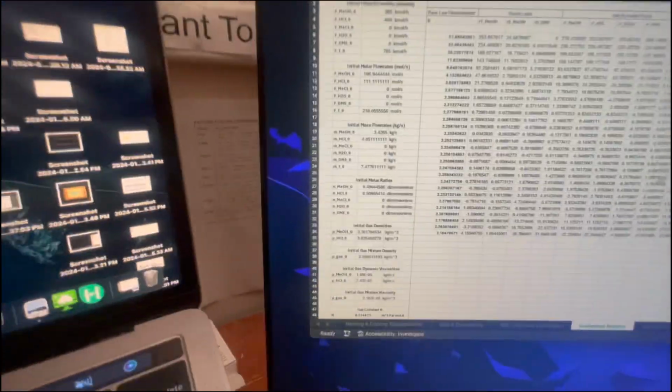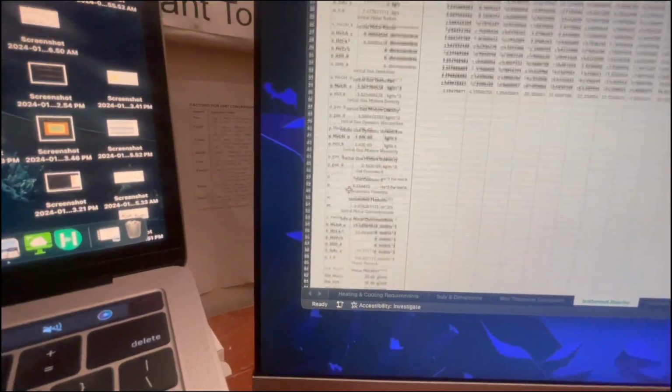The only thing is the reaction rates are pretty high, because those rates are found using a micro reactor. A micro reactor being very small, it doesn't take long for the gas to disperse and react. So the rate of reaction will be higher than in a large reactor, and these kinetics might be too high. The next thing to do would be to see if I can scale down these values a little bit to get more accurate results. That'll probably be it for the isothermal case.